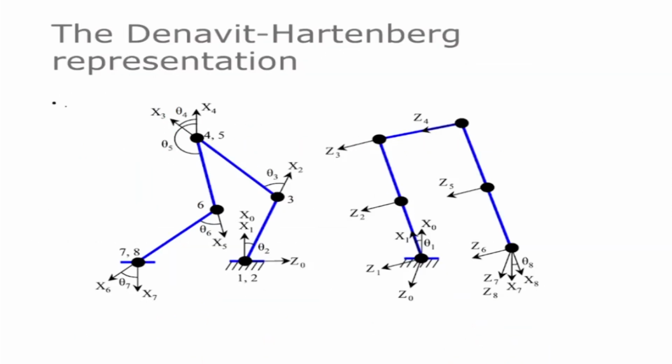The first thing that we have to see is we are going to model this as a serial link manipulator. One of the feet, which is on the ground, is fixed onto the ground, and the other joints are moving forward with a particular trajectory. So this rear leg is moving like that and becoming a front leg. This one is the fixed base. So it's like a serial arm, and you're doing the inverse kinematics with an 8 degrees of freedom system now. So now we are assigning our DH parameters.